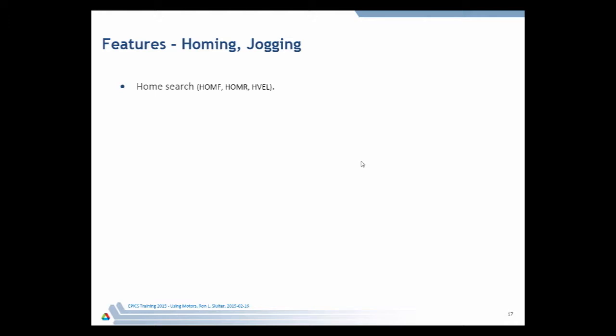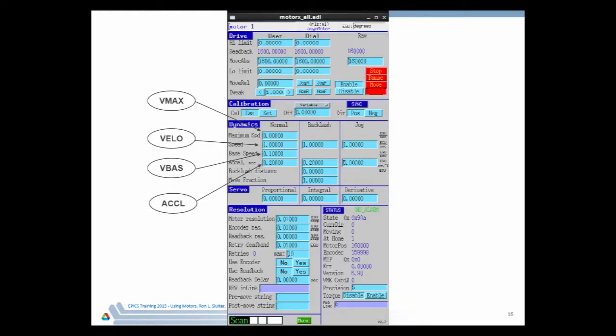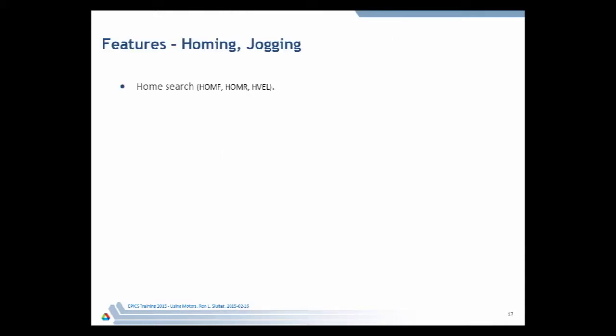No, it's not a time from zero. Again, it depends. If you're dealing with a servo and you have your base velocity set to 0, then yes, it is the time from 0 to the slew rate. So you're basically setting how long it takes to get from the base velocity to the slew velocity; you're indirectly setting an acceleration rate. I think he's asking, if you have a base velocity, how long does it take to get from 0 to the base velocity? Oh, it's instantaneous.